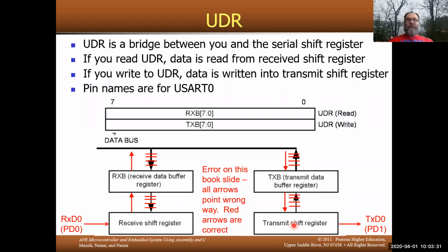And there is a flag that's set saying the transmit data buffer register is empty. So I could either poll that flag or I could tie it to an interrupt. And then if I've got an array in C, which we may look at today or next time, I could take the next character out of that array and write it to the transmit data buffer register.